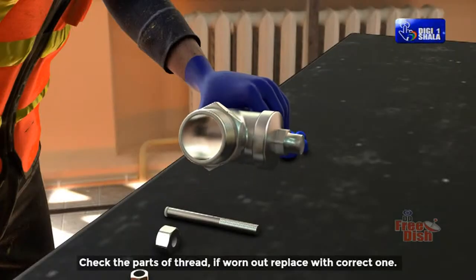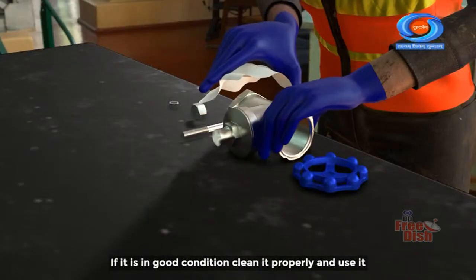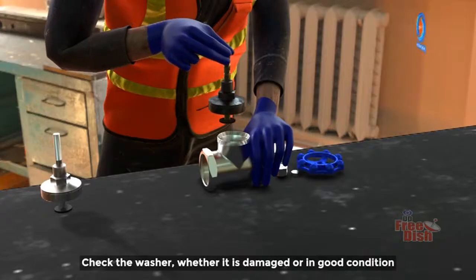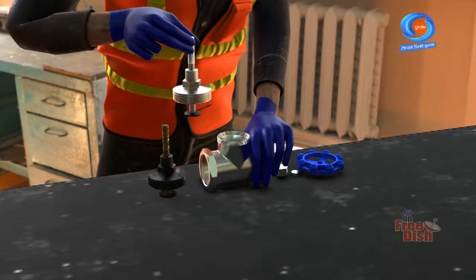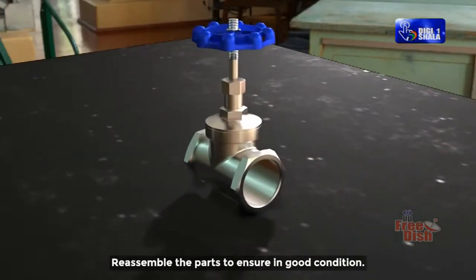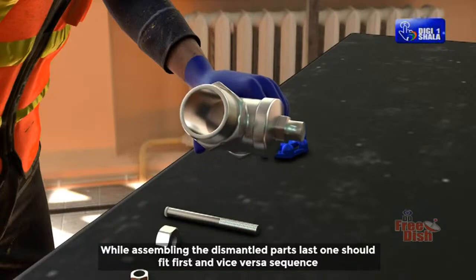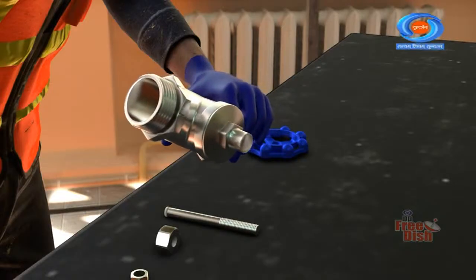Check the parts of thread. If worn out, replace with the correct one. If it is in good condition, clean it properly and use it. Check the washer, whether it is damaged or in good condition. If damaged, change the washer. Reassemble the parts to ensure they are in good condition. While assembling the dismantled parts, the last one removed should fit first, and so on in the reverse sequence.